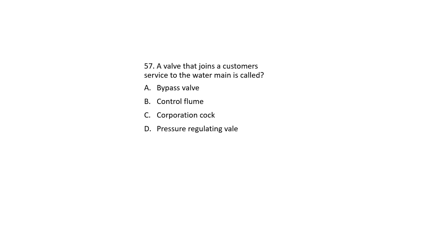A valve that joins a customer service to the water main is called a bypass valve, control flume, corporation cock, or pressure regulating valve? The answer is C. I normally hear people call it a corp stop in distribution.